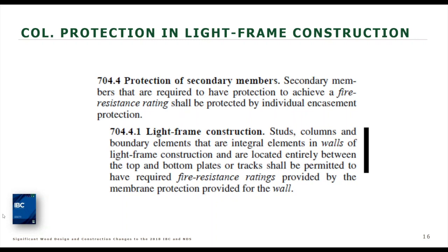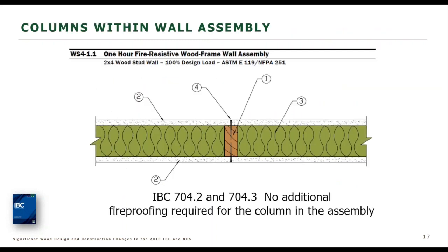And so that clearly spells out that if you have, from our DCA 3, a 1 hour fire resistance rating, and it needs to be protected from both sides, in this case where we have a column that is in the wall, no additional fire resistance is required for this, provided that this is a fire resisted assembly here.